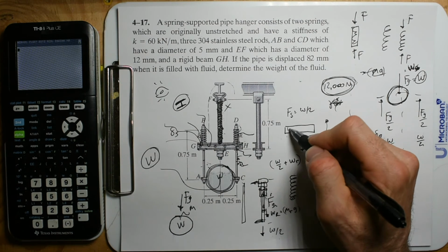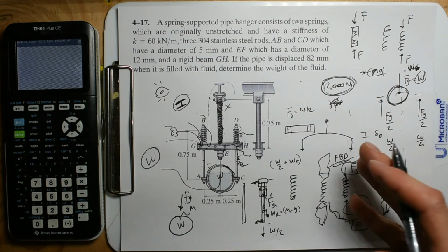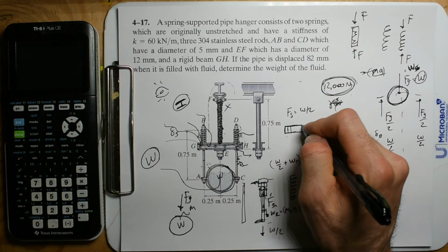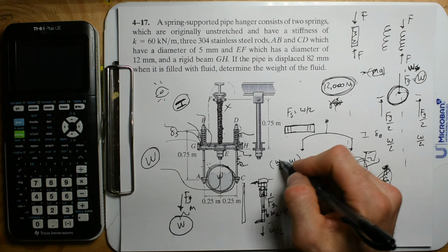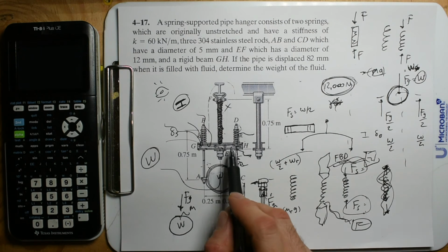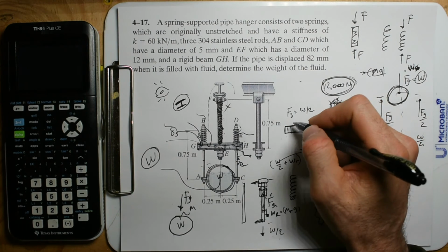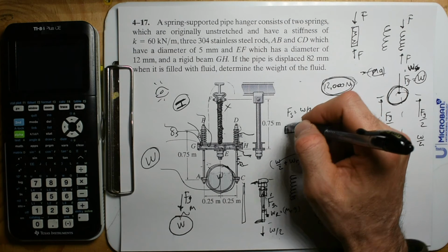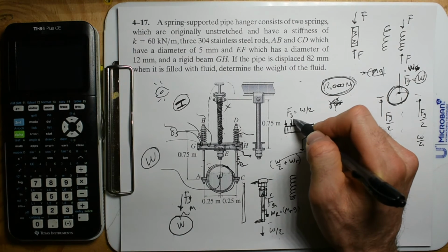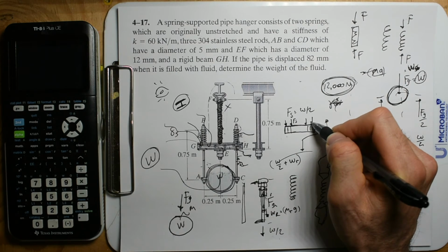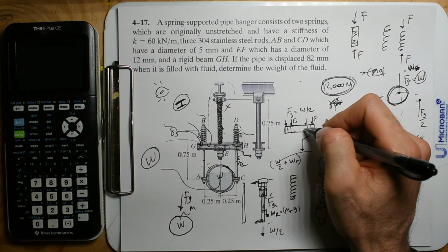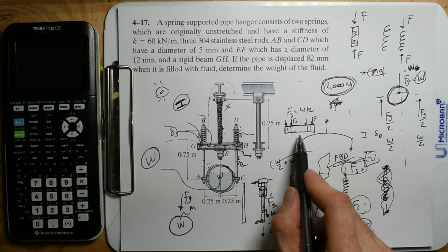So that's for the free body diagram. We're going to float this in outer space, and then we want to know what's touching it. Or if it has mass itself and there's an earth underneath us, but we're going to say this is a massless beam. And we have the springs. The springs are actually touching it, so we have the force of the springs, and we have both of them. So we have 2 times the force of the springs. Is anything else touching it?